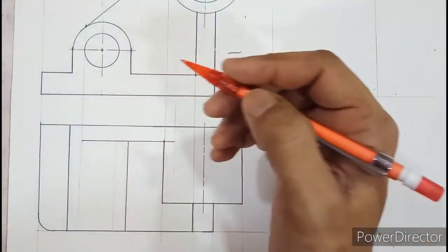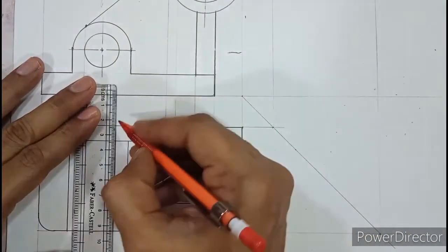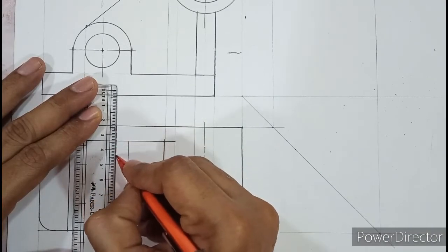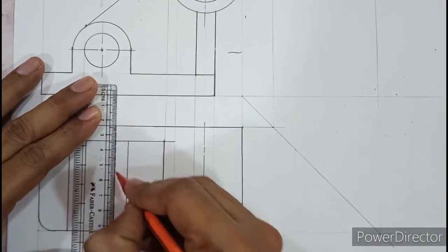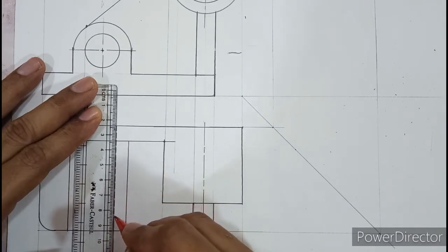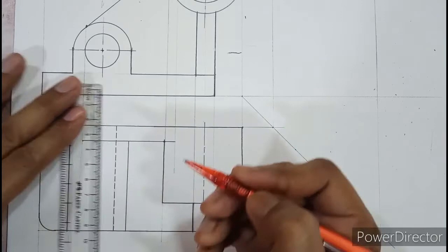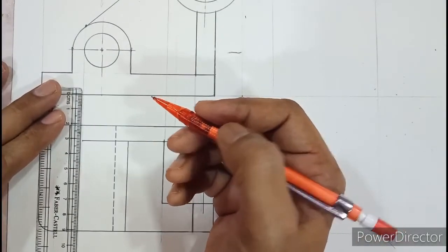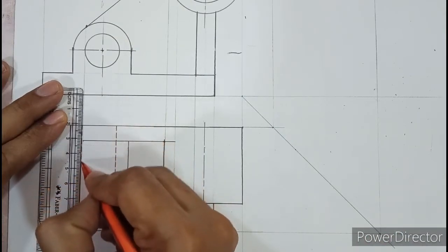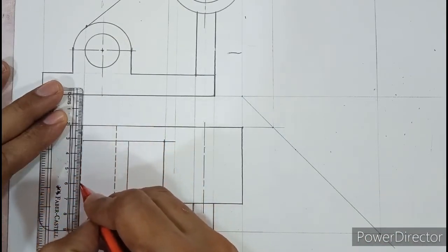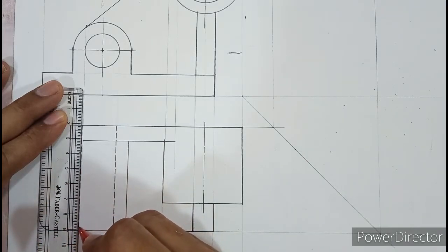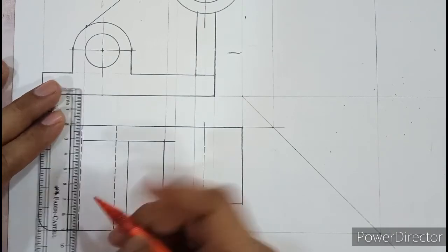Yeah, so that hidden line is throughout. So I will keep the scale over here and we will draw neat hidden lines, and you have to follow rule number 1 that the hidden line should intersect the dark lines at both the sides, and even on this side these are the hidden lines. See, the last hidden line can be longer a bit to make it to intersect.